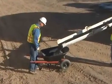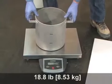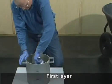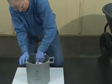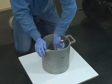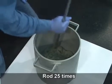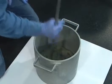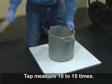Begin by properly obtaining a representative sample of fresh concrete. Then, determine the mass of the empty measure and record this value. Using the scoop, place the first layer of concrete into the measure. Move the scoop around the measure to distribute the concrete. Consolidate the concrete by rodding the layer through its depth 25 times, no more and no less. Now, tap the exterior of the measure 10 to 15 times with the mallet.